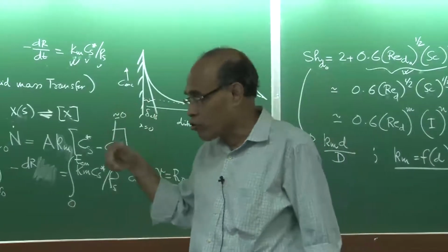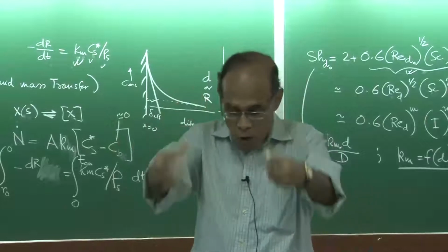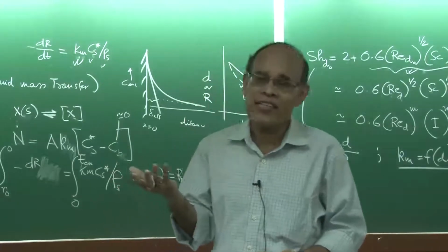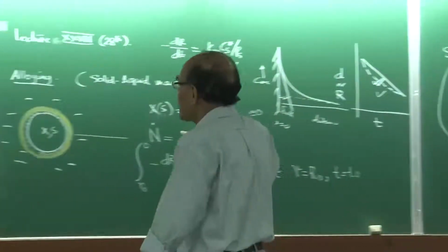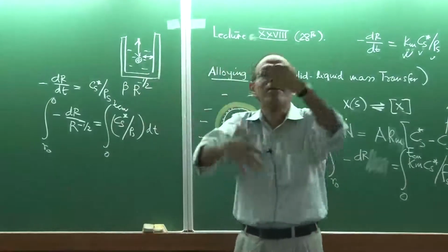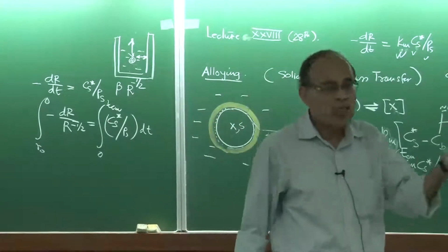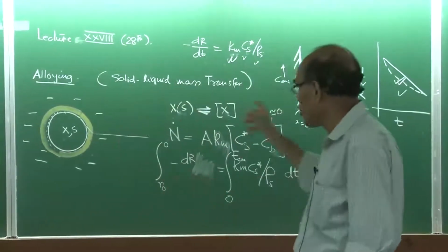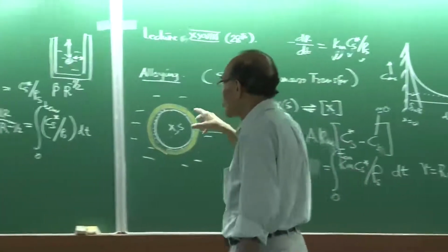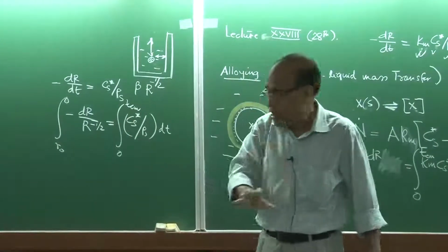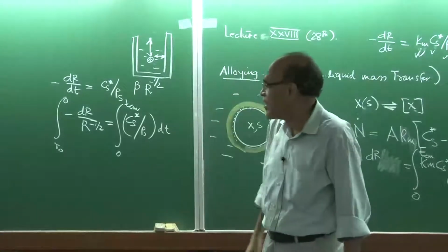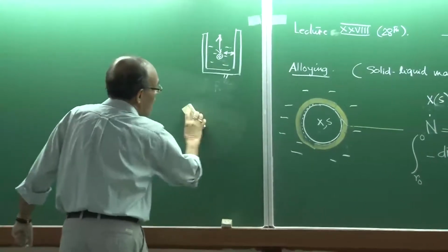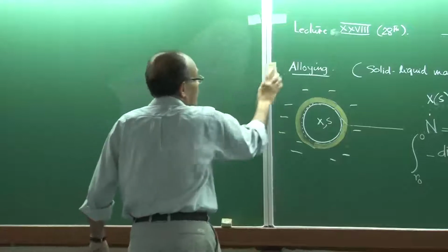But if you compare that, after dissolution, how much time will they take to homogenize into the bath, you will find it is possibly only 50 seconds or 100 seconds. So by the time the dissolution is complete, actually the bulk remains well mixed, and in most metallurgical systems, because there is stirring always present, the subsequent mixing following dissolution is not a matter of concern. So it is the dissolution that needs to be properly engineered in terms of stirring, as well as the size ranges that one would like to add to make the alloying additions practical.